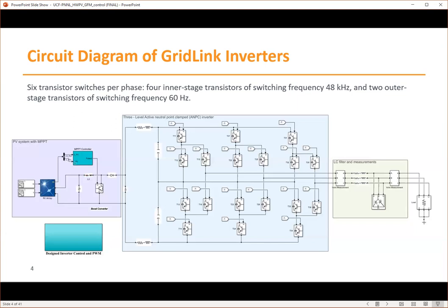And for the PV inverters, of course, it has the MPPT, the DC boost converter at the front, followed on the output side by the standard LC or LCL AC filter. And that's the basic configuration that we'll be using in terms of designing control and developing dynamic models.